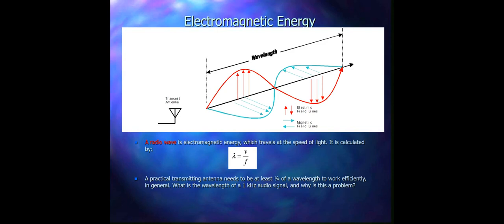And there's another type of polarization which is called circular polarization, and it is often used in satellite communication because of the relative orientation of the receiver and the transmitter, which is hard to control. So that's why circular polarization is much better in those kinds of applications.